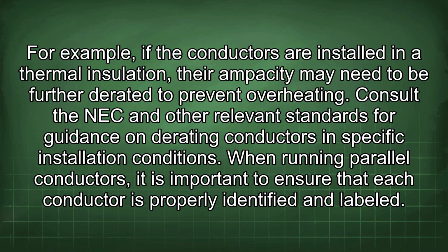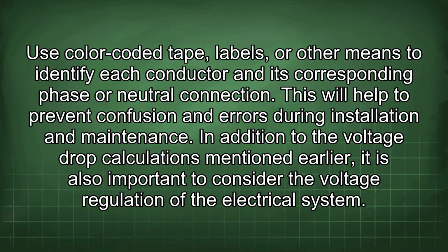When running parallel conductors, it is important to ensure that each conductor is properly identified and labeled. Use color-coded tape, labels, or other means to identify each conductor and its corresponding phase or neutral connection.